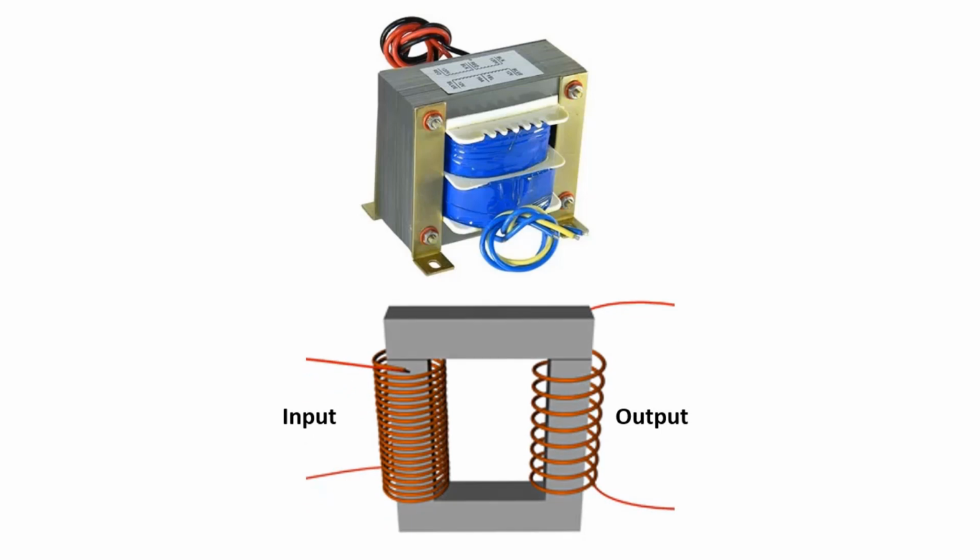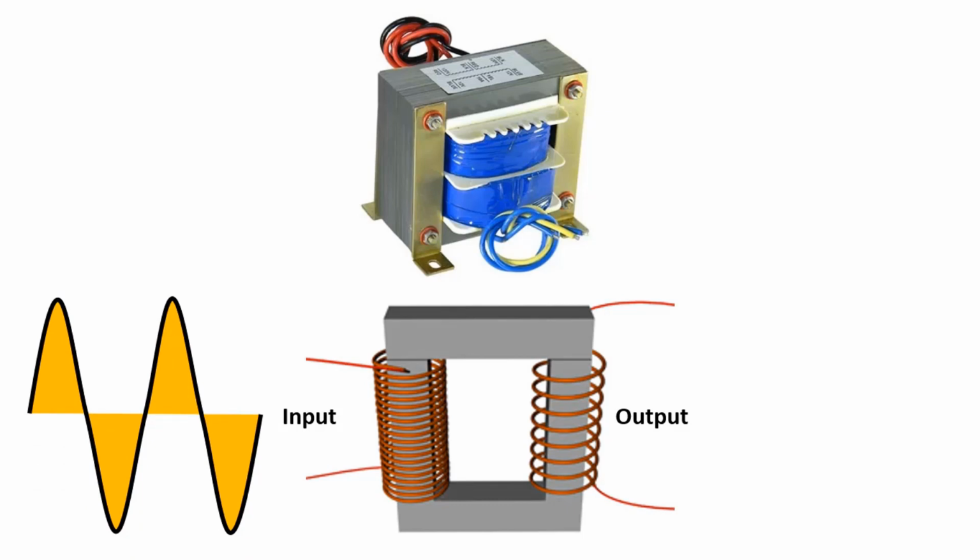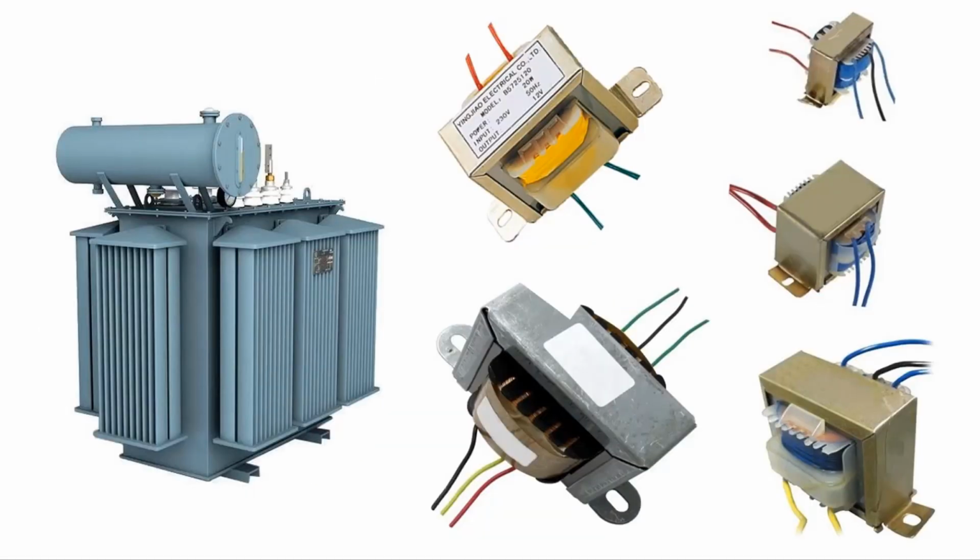In the internal structure of the transformer we see here, since there are many windings at the input and few at the output, we can say that the voltage value of the sinusoidal wave at the input is reduced at the output. If we do the opposite, we will increase the input voltage. But in direct current, it is very difficult to obtain very high voltages by increasing the voltage value. Transformers simply step up and down AC. Of course, larger transformers are used to achieve much higher voltages. Very high voltages cannot be generated in DC.